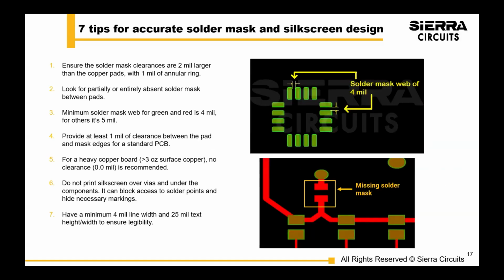Solder mask. Okay, solder mask and silkscreen. For solder mask and silkscreen, really these processes are more for the assembly facility rather than the fabricator, yet the fabricator makes decisions on what is manufacturable. And if you're not working with someone who does both fab and assembly, you're going to get partial feedback. And it really limits your ability to make an overall assessment and overall design decisions. So I highly encourage working with a fabricator and an assembler, and of course Sierra is both.